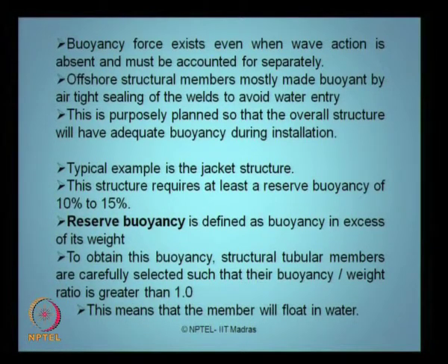You must select the tubular member in such a fashion that the displaced volume of this member, compared to the weight of the member, with respect to its cross sectional dimension and thickness, will always satisfy that the buoyancy will exceed its weight. This is what we call reserve buoyancy. If you have a member of this nature, then this will enable the member to float in water during installation.